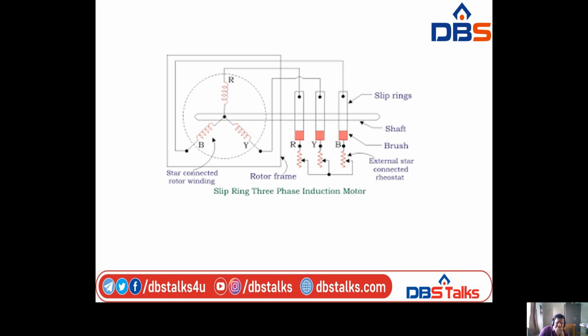Because of this external resistance connected to the rotor, this slip ring induction motor has high starting torque, because starting torque is always proportional to the resistance. Here the resistance is available externally, whereas in the squirrel cage induction motor, the conductors are enclosed with end bars and end rings. That's why there is no external resistance we can put into the squirrel cage. That's why it is not utilized for high starting torque purposes. It may be utilized for medium or low starting purposes.